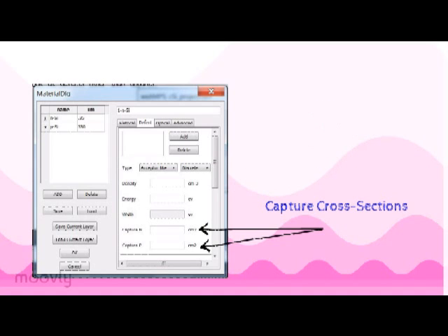We can also define the capture cross-sections. These are like the size of the target for incoming carriers. AMPS allows us to model doping levels and other defect states as localized states that form a continuum throughout the bandgap. These continuous distributions are different from the discrete or banded localized gap states, which only exist at specific energies or at a specific range of energies in the gap.